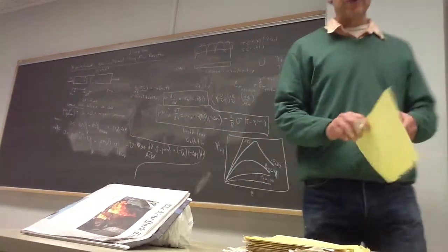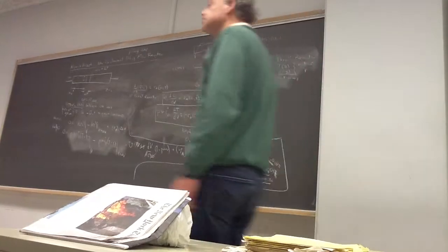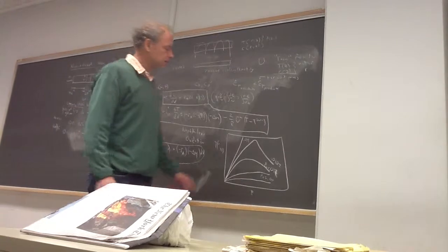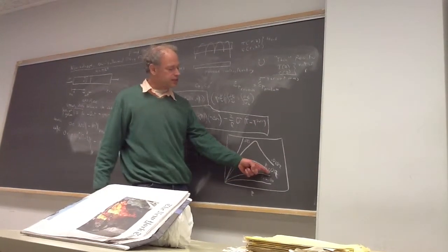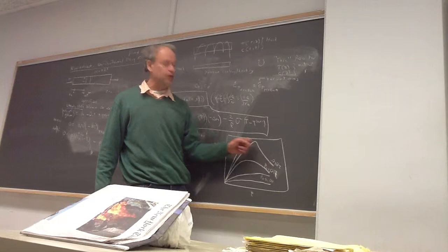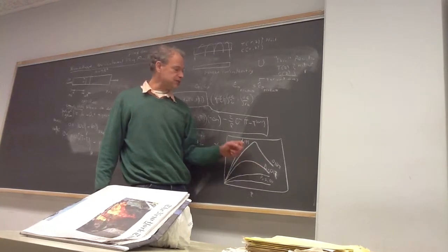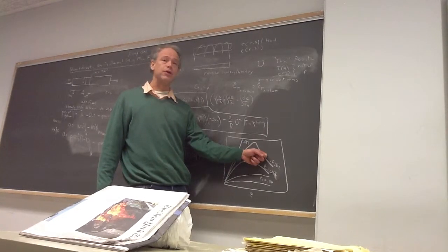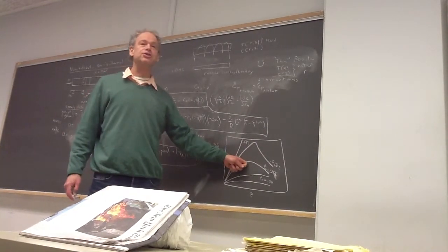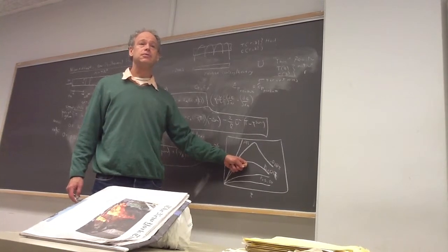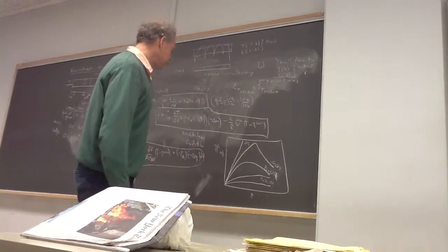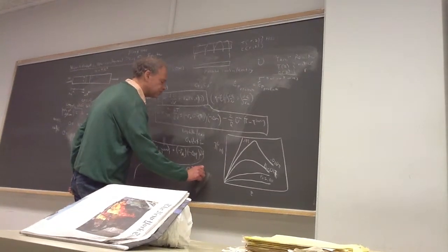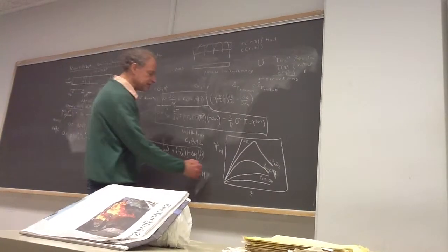So I want you to notice what's going on here. At very low concentrations, there's no problem, but there also isn't very much reaction, so I haven't produced very much. Once I get to higher concentrations, and look how little the concentration changes between here, here, and here. Between 0.017 and 0.019, I have drastically different behavior. But what you see at 0.017, 0.0182, is that the temperature goes through a maximum. So the first characteristic here is there's a T max as a function of z at a particular z max.